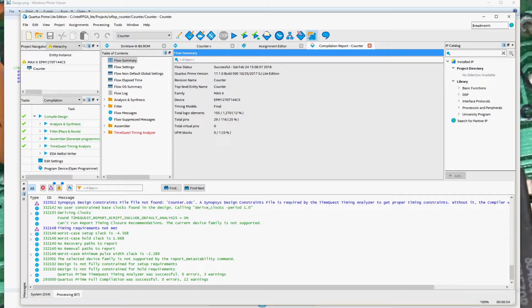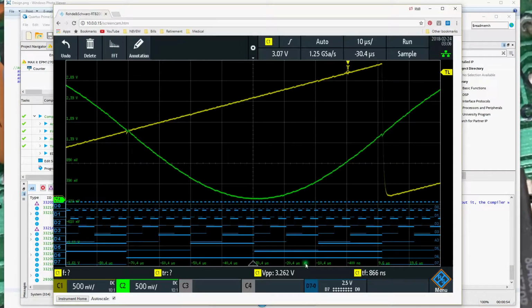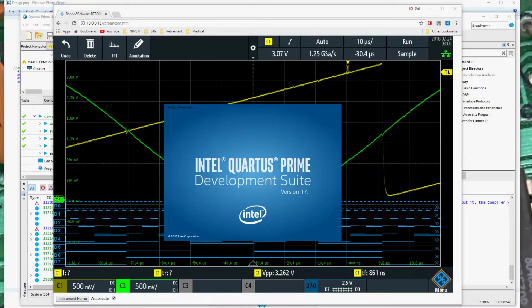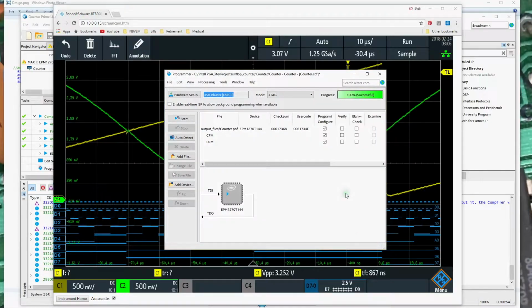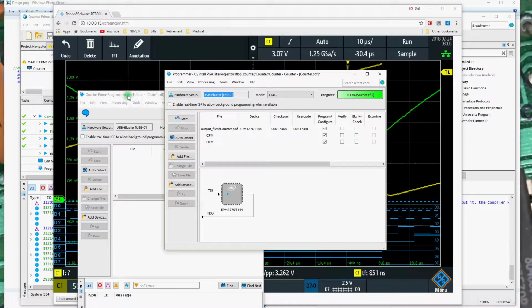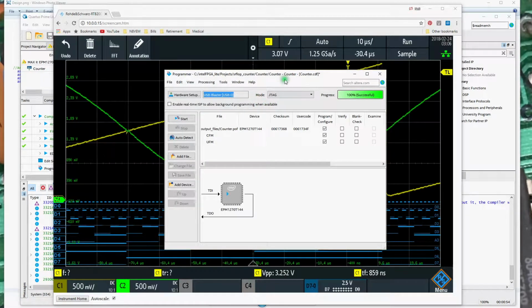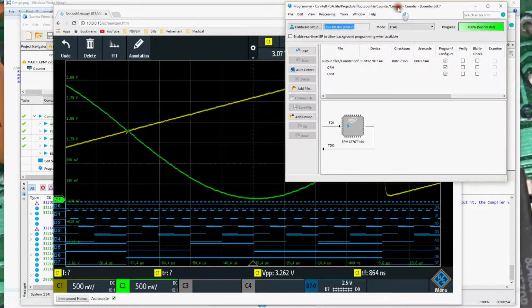And we're done. For this case, I'll go ahead and bring up the oscilloscope display, and then I'll bring up the programmer as well, if it'll load here. Oh, I did not want to do that. I actually ran a second version of it. So right now we're running on the previous download to it, where we had shifted the bit up to 12. We've now shifted to 10.